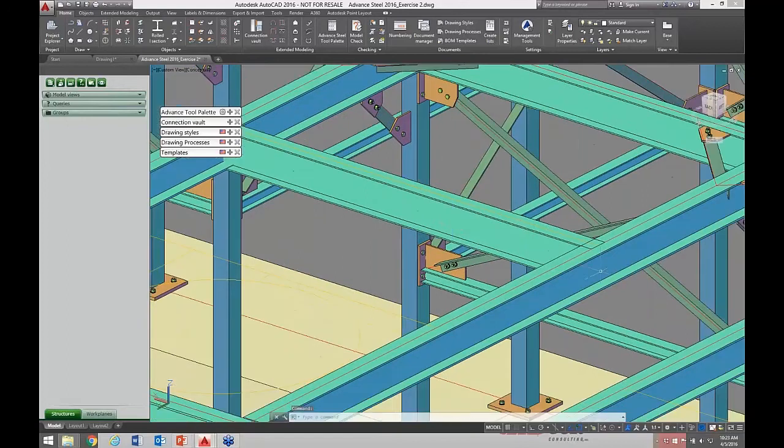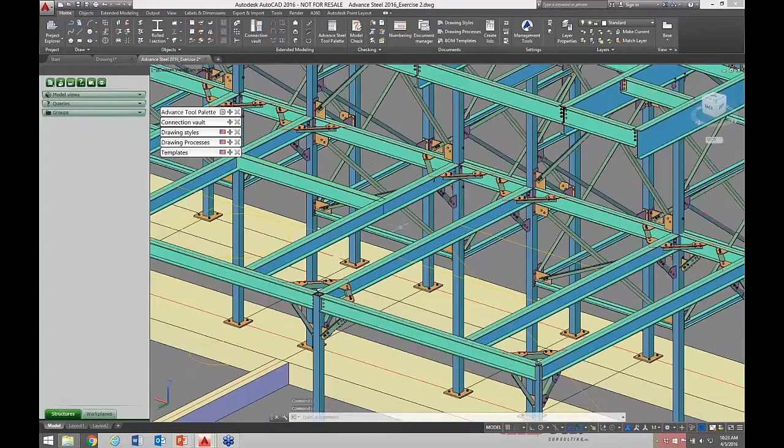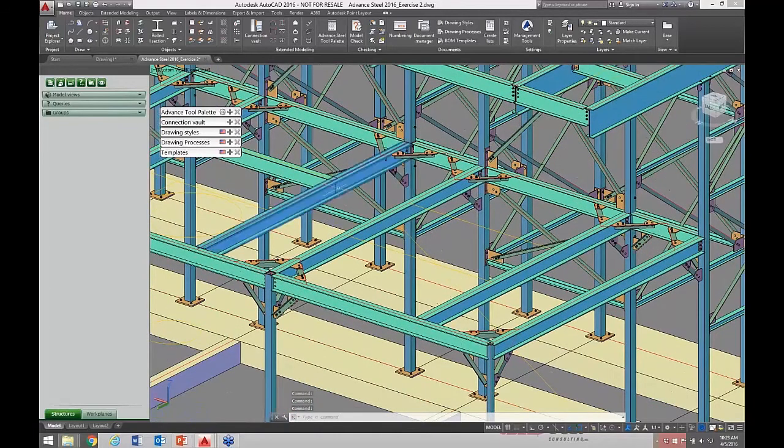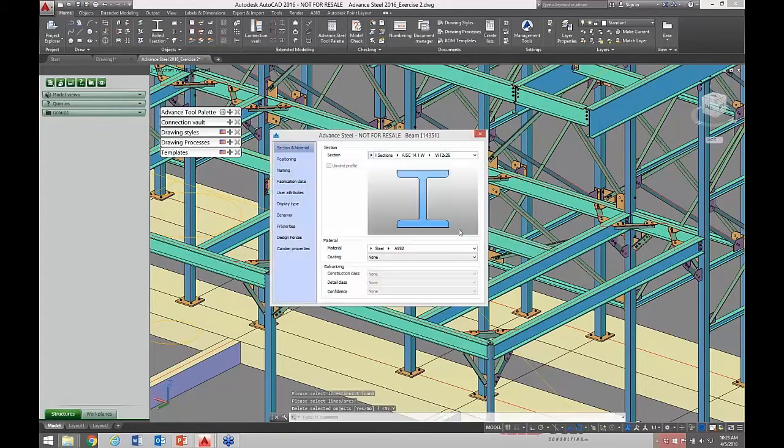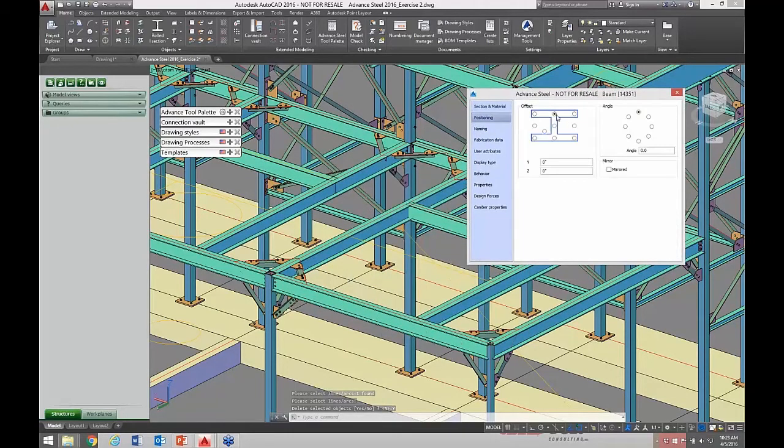All right. That was one method, just simply point and shoot. I was choosing what type of element to model and snapping point to point. You would also find that we have the capability to do something called a beam from a line. If I have one of those AutoCAD lines, I can simply start that tool and click my line, or more than one. I can keep the reference information if I want or get rid of it, and it's the same process. I get access to my properties.